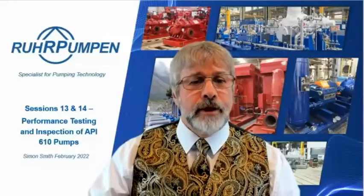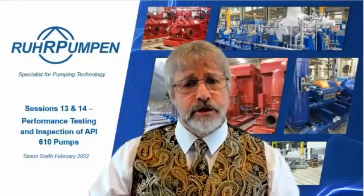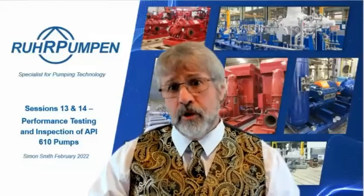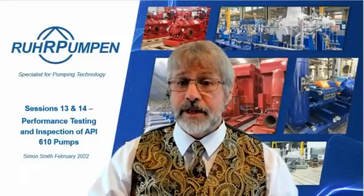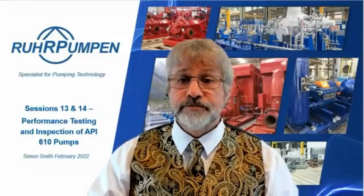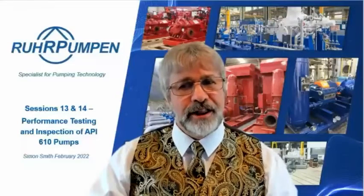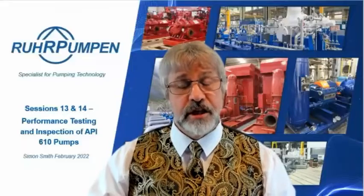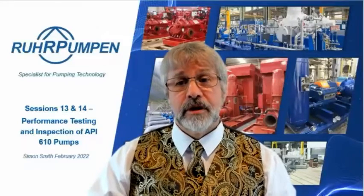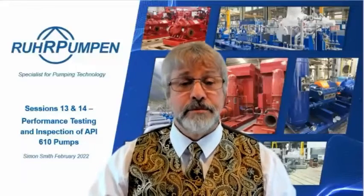Shyam Kumar, the NPSH test to be performed for both the A, working, and B, installed spare pumps, or only one pump? Well, generally it will be done on all the pumps, but again, you can specify that if you only want one NPSH tested, that will be fine. Perhaps if NPSH is not a critical issue, if you've got ample NPSH margin, then you might be prepared to waive the NPSH test on the second pump.